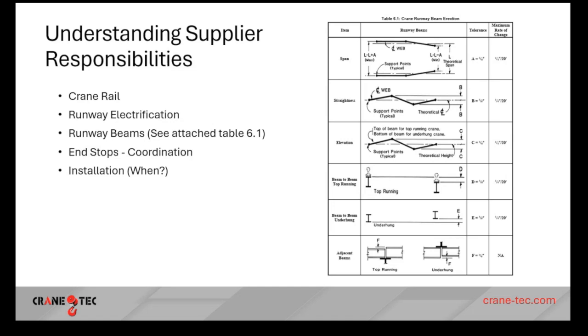Yes, sir. It makes a lot of sense. So, yeah, I don't know if there's a silver bullet answer to that, but I've seen some ugliness out there where tolerances can't be achieved. And I had one job in particular where the beams had to be effectively remanufactured because of what you're describing. And the crane techs of the world obviously aren't going to warranty the crane system if it's basically running up and down that aisle like on a roller coaster track.